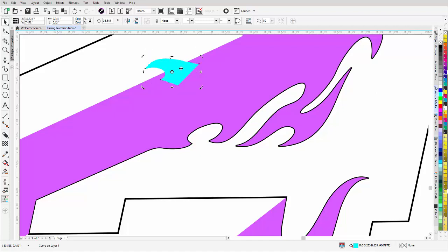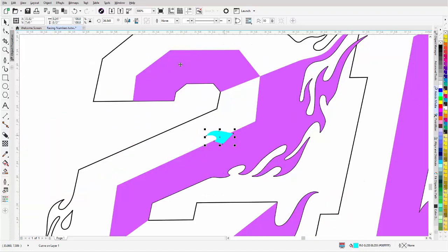that, and I can just fit that in here any way I'd like to, coming down through here, put one here, scale it down a little bit, put another one, and I got my center point there. I didn't want that. Left click, right click one time to duplicate, bring that down here. Maybe I'll rotate that and then resize that a bit. Then we'll just go ahead and hold down Shift, select, select, select, multiple object property bar, weld.